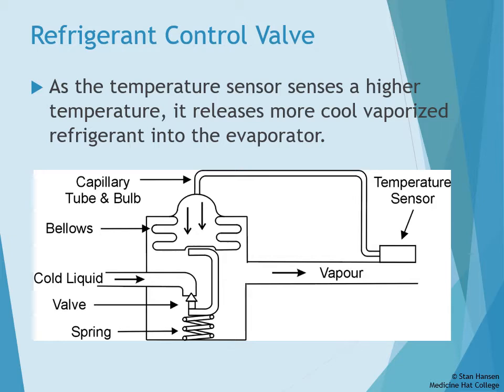The refrigerant is a liquid that easily changes from liquid to vapor and back again. Typically, we would use Freon or chlorofluorocarbon gases, or CFCs. Keep in mind these are both bad for the environment, so it is illegal to let them disperse into the air. The refrigerant will have a pressure change happen inside the valve. The high pressure warm refrigerant goes in from the condenser coil and the low pressure cold refrigerant leaves to the evaporator coil, and the pressure change is a result of the change in pipe size.